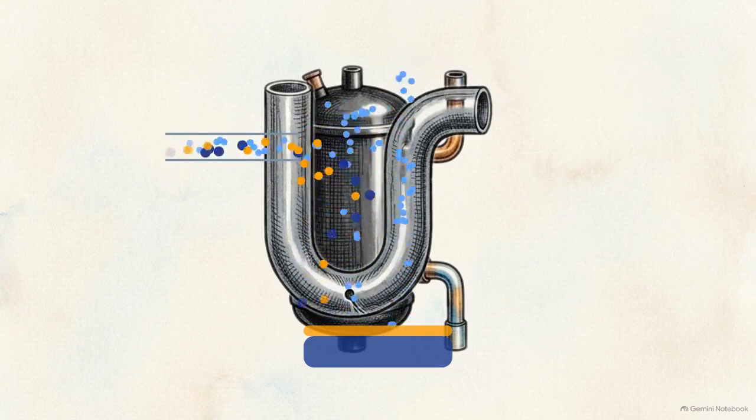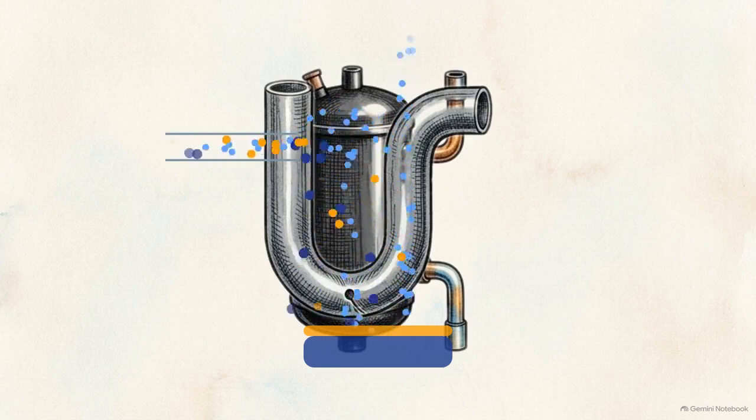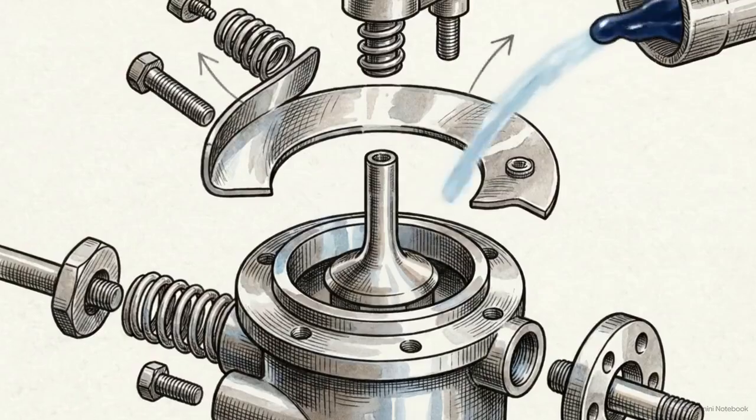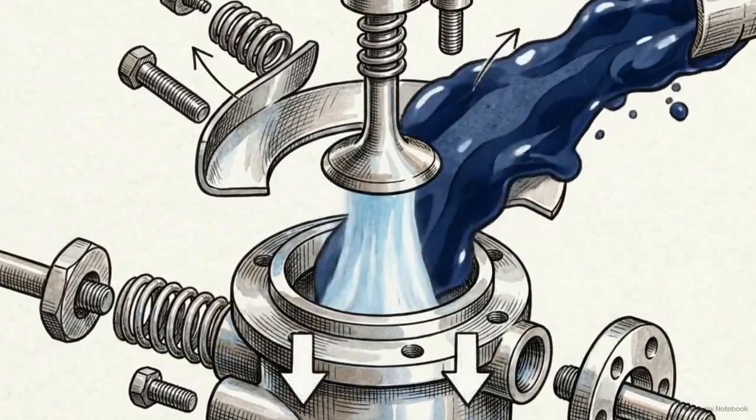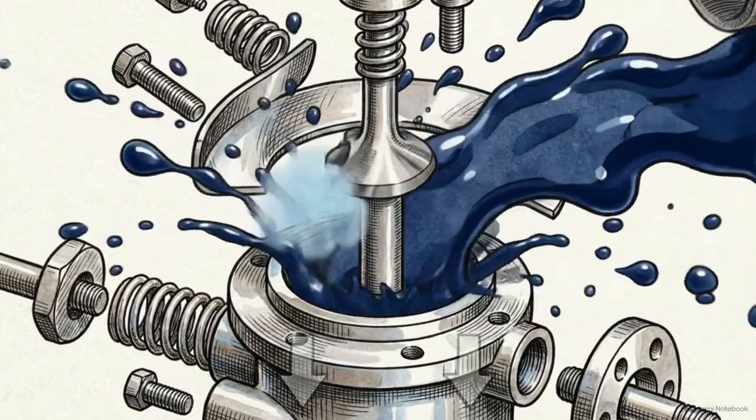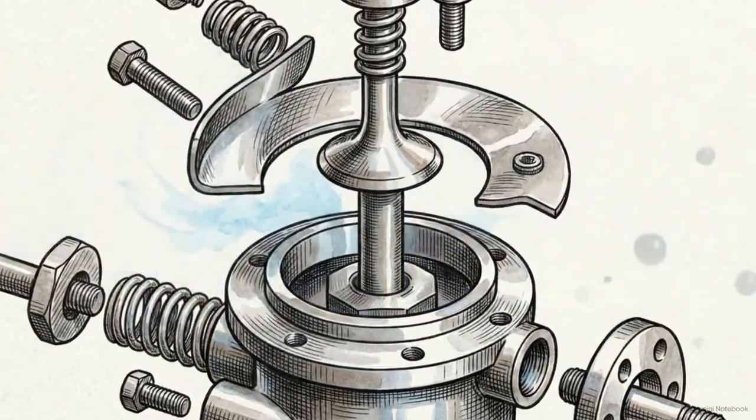This decoupling occurs continuously, allowing the system to handle dynamic changes in refrigerant flow without interruption. By utilizing geometry to manipulate fluid velocity, the accumulator strips the dangerous liquid mass out of the flow path before it can reach the compressor.